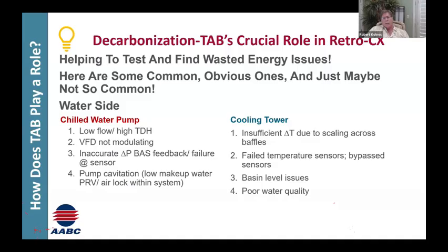I'd initially take a look at the makeup water assemblies, see if the isolation valve has been closed, or if the pressure reducing valve has been adjusted lower, or if it was replaced with an insufficient range. Those are contributing factors that would lead to a low net positive suction head available.